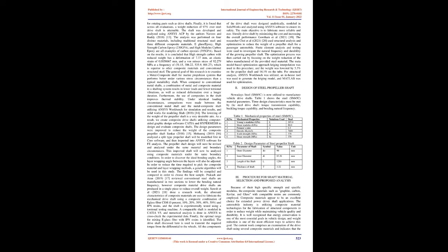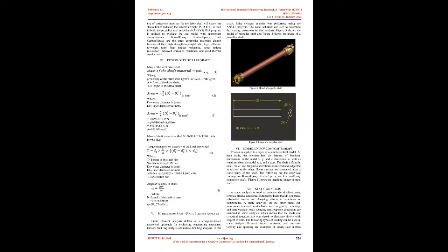Using hydrodynamics and structural analysis, Chen et al., 2017, 11 present a composite propeller blade to increase efficiency and to lower acoustic emission. For analysis, finite element, FE, software is employed, and Ansys Fluent is used to model the hydrodynamics surrounding the propeller. The findings emphasize increased MCP performance and discovered the morphing composite propeller arrangement has improved efficiency by 1.1% while boosting structural durability.